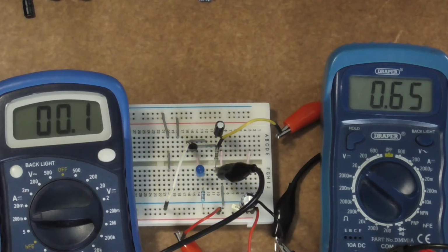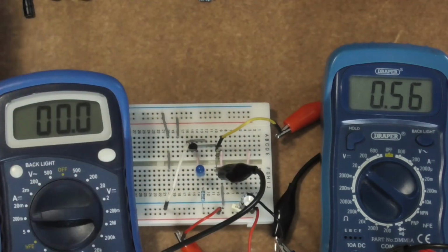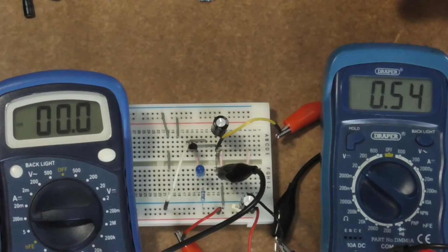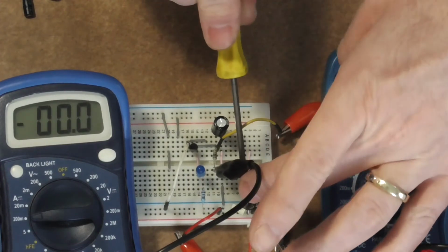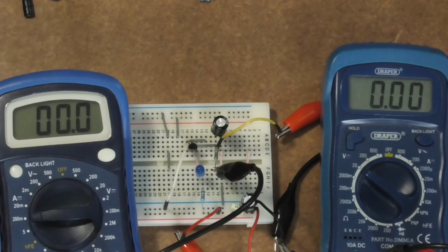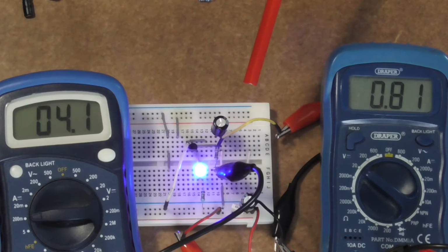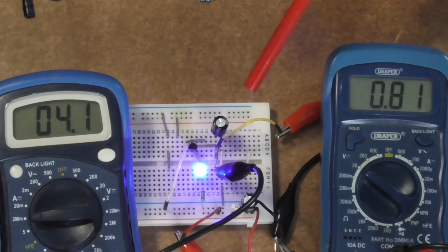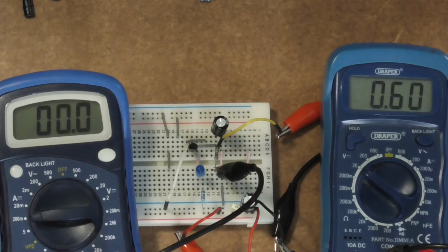So I bet if I was to change capacitance, let's just jump straight up to the 330. No messing about here. Let's see what happens with the 330 microfarad capacitor with that 1k resistor. Again, we've got the same scenario, a lot less current and slightly less voltage, but it still comes on pretty instantly, doesn't it? It's not a problem, it works, it turns on, it's instant, or it appears almost instant.